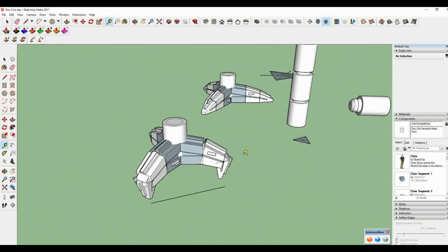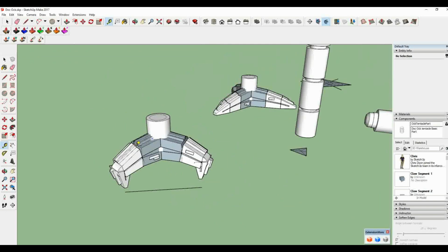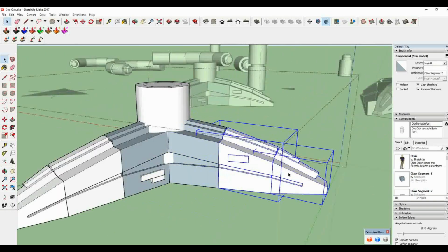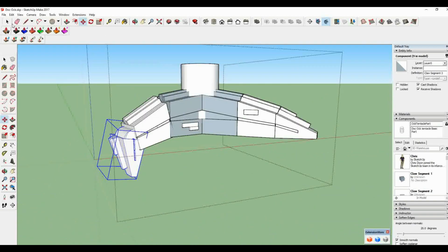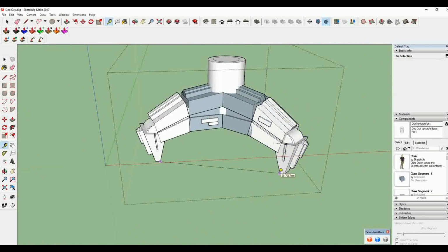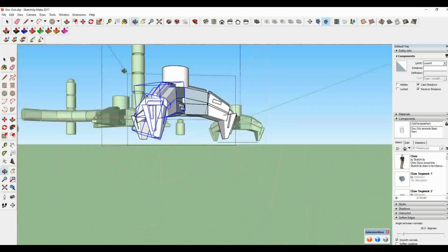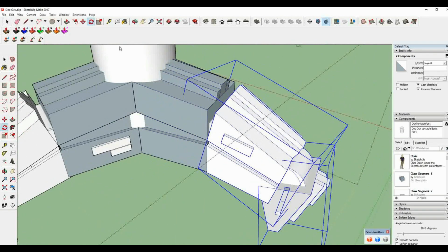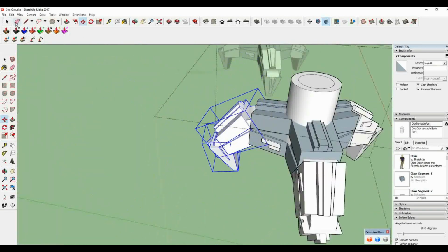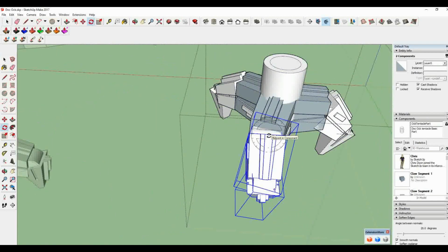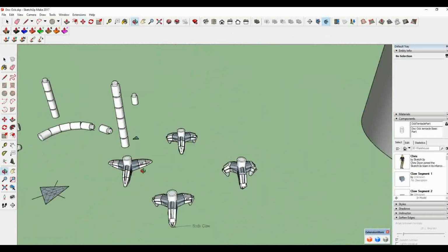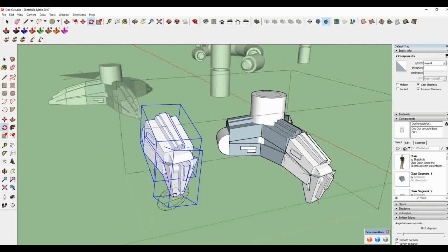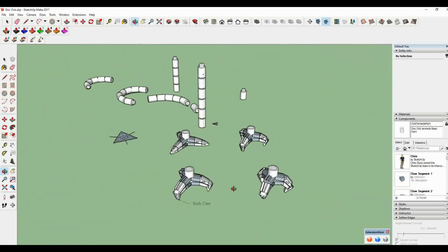After I had the one claw done, I wanted to vary the other three with a progression of a claw gripping at something. I start by making a copy of the first one. When I designed the first one, I included an internal knuckle joint. When I rotate at that spot and the insides are revealed, the knuckle joint will be exposed, making it look like it has some internal parts and not just a split between the two finger segments. Once I have the angle of the claw fingers, I copy that, rotate it, and place it on the other two fingers.